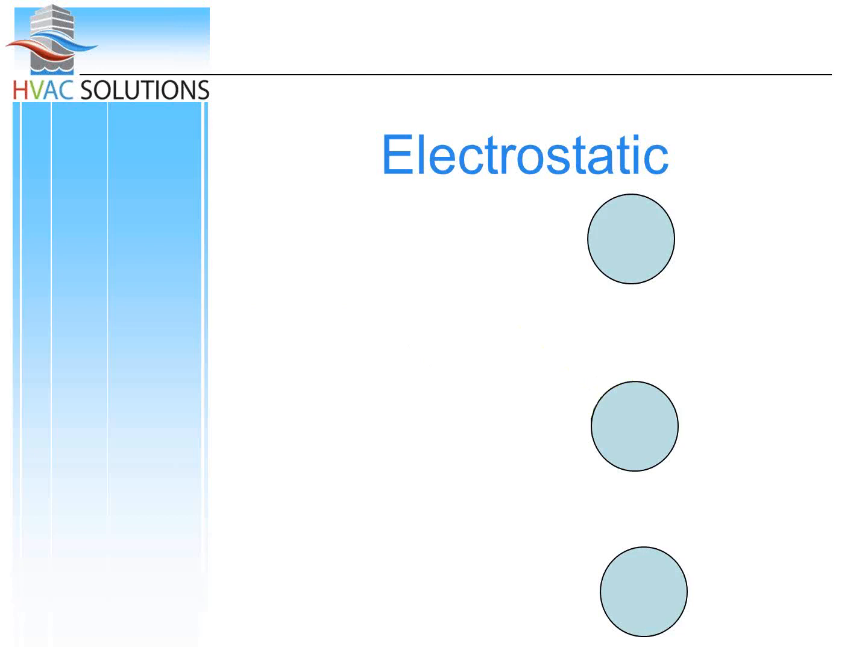A few other concepts, depth loading. So depth loading is the opposite of face loading. Face loading is where you pull out a filter, the side of the return is dirty, the side of the furnace is clean. Everything gets caught on that front side, and anything that gets pushed through gets caught on the coil.